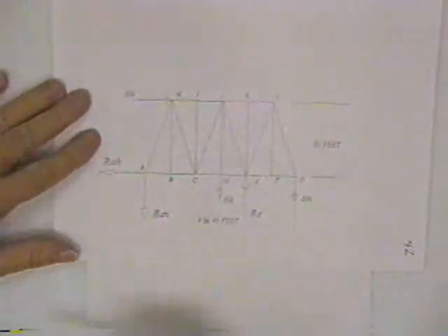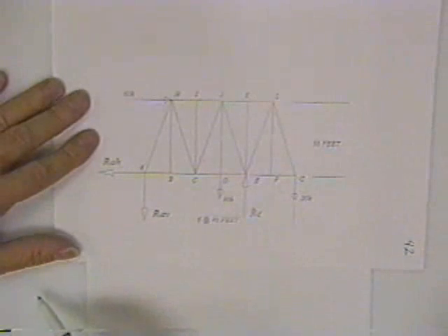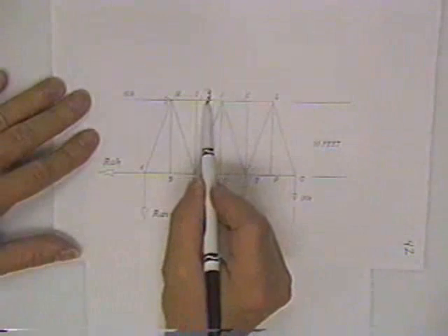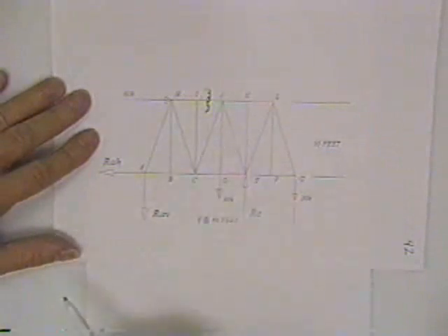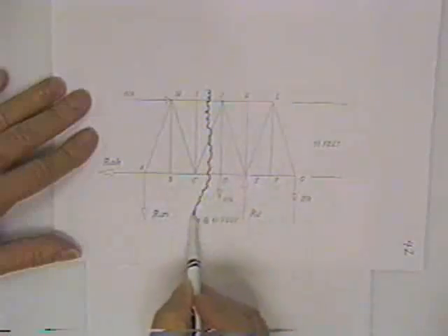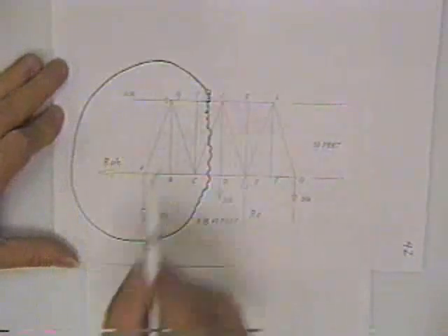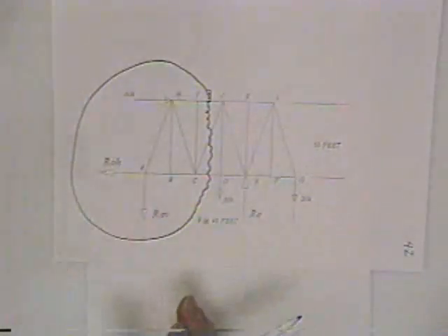Alright, now, to solve for the force in member IJ, you must cut member IJ. Then, cutting as few members as possible, you would come on down like this, circle either end of the structure, and that would be your free body.